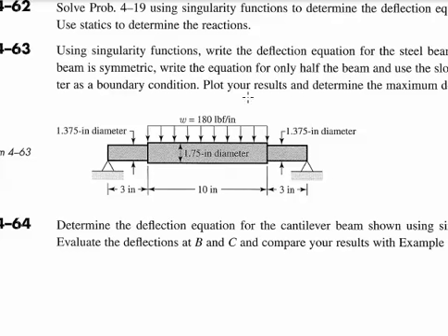And so to find the deflection in the middle, we will place a dummy load Q in the middle. We'll have to do some statics to find one or the other of the reactions. We don't have to find both. But notice our problem is symmetric again. And if we're wanting to calculate the deflection in the middle, then even Q keeps the problem symmetric. And if the problem is symmetric, I don't have to integrate energy all the way across the beam. I can just do energy halfway across the beam, and that gives me half the energy. And then I multiply by 2 to get the whole energy. It saves me just a little bit of work.